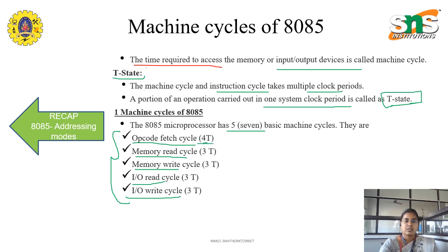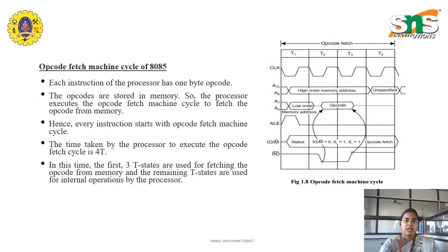These times are the T states for each fetch cycle. And here you can see T1, T2, T3, T4, that is the total T states. The opcode fetch comprises 4T. The first one is the clock signal. We have a clock signal here.